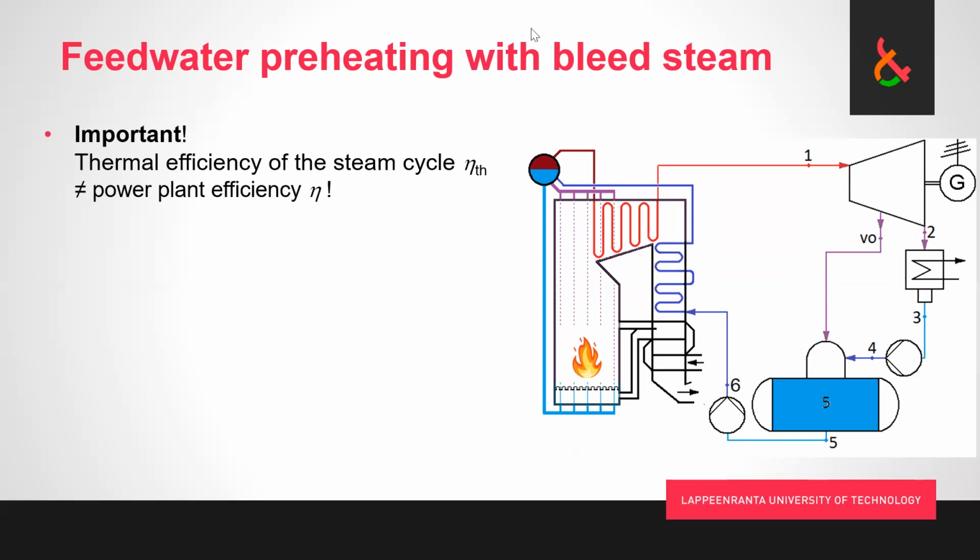So for that purpose, I've drawn here a picture of the boiler, what happens here. Normally if you put feed water in the boiler, you can heat it to a pretty hot temperature, and it goes into the boiler in what is called the economizer. That's the feed water preheater that gets the water very close, not quite at boiling point temperature, before putting it into this so-called drum.